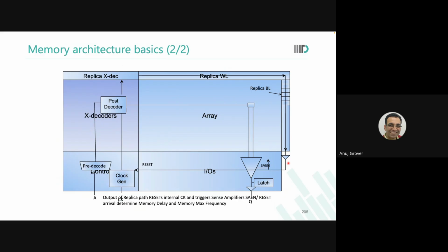So now when you are verifying your design, do you realize it is not necessary that this is the worst case cell or this is the worst case sense amplifier? Depending on where you placed your signals and what kind of tracking you did, the worst case could be right adjacent to the control region also.